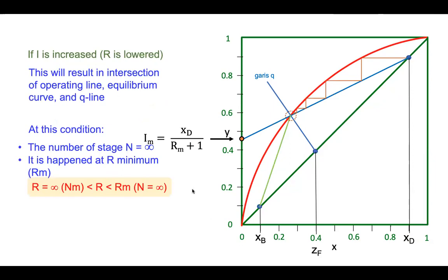So the minimum stage of equilibrium happens when the reflux is infinity or maximum, in total reflux. However, if we drag the line up there, the maximum of the top line would be the intersection between the Q line and the equilibrium line. Why? Let's have a look at this one.